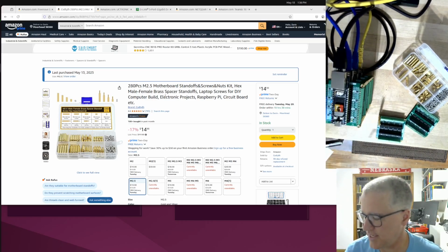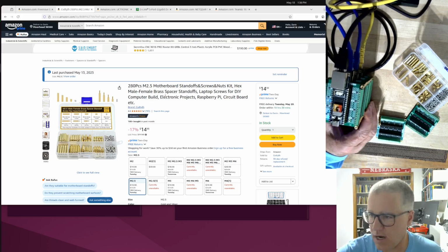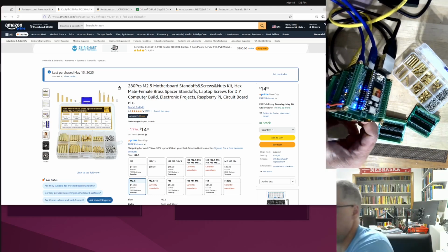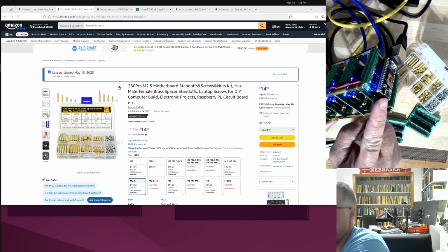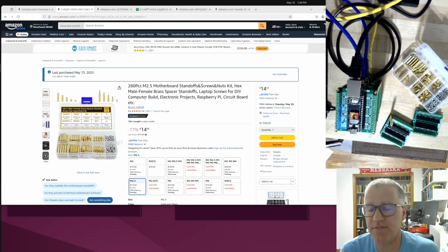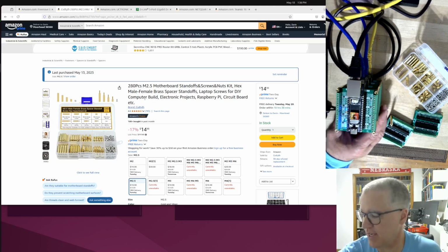So nice easy setup. I'm powering the LuckFoxes not through their USB-Cs. I've actually reconfigured the LuckFox's USB-Cs so that they can act as a host rather than a device. So we can plug in USB drives and other things like that.